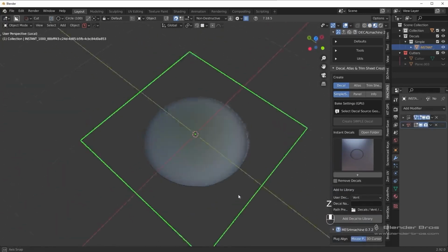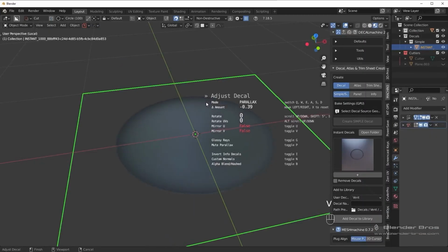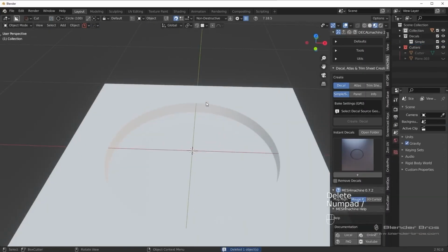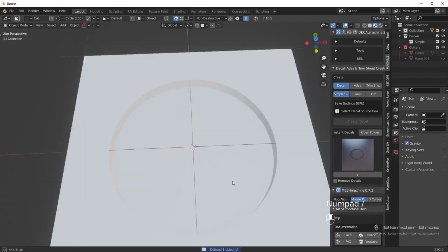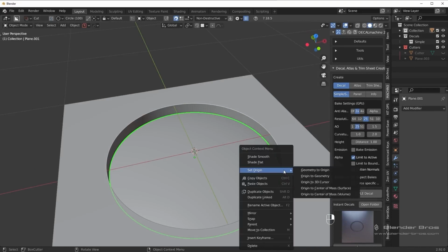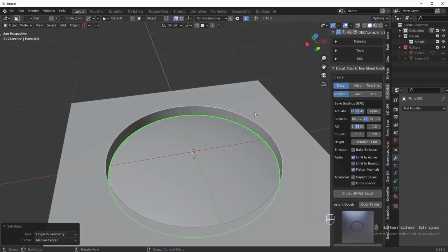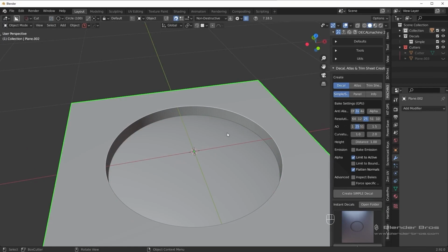There you go. And as you can see, it actually isn't the outer plane causing problems. It looks like it's the actual decal that's being a bit of a nuisance here. So we're going to have to fix that. A nice and simple solution would be to just take this decal and use it as a subset decal, which means you have two separate selections. So we could select the decal, shift click the outer plane, and then create a subset decal this way. Not really an issue doing it this way, it's just that you'll have an extra material slot, which is kind of a waste.